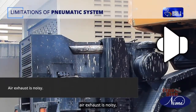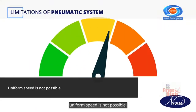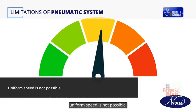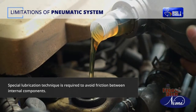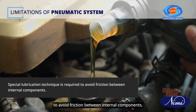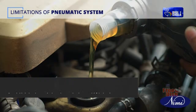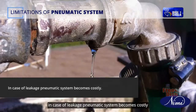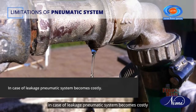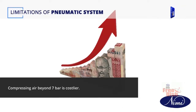Air exhaust is noisy. Uniform speed is not possible. Special lubrication technique is required to avoid friction between internal components. In case of leakage, a pneumatic system becomes costly, and compressing air beyond 7 bar is costlier.